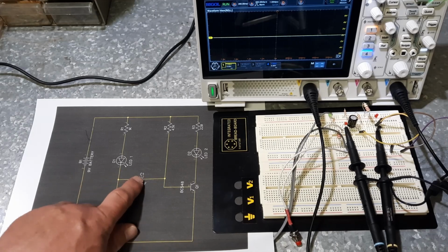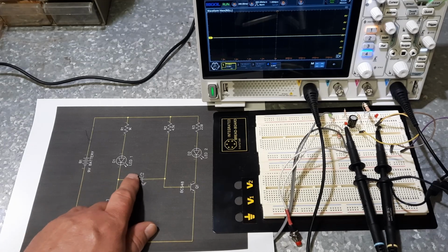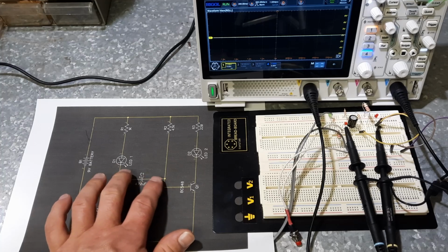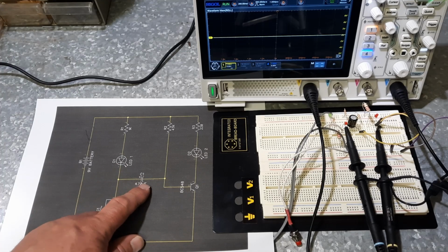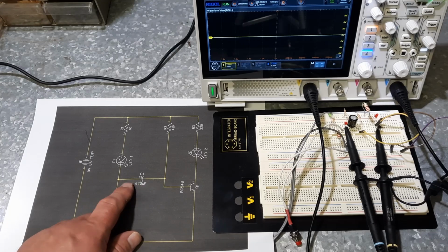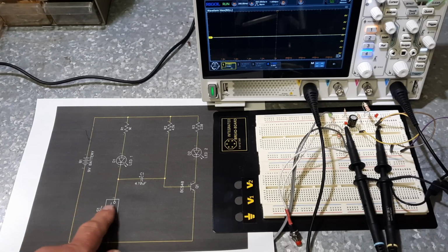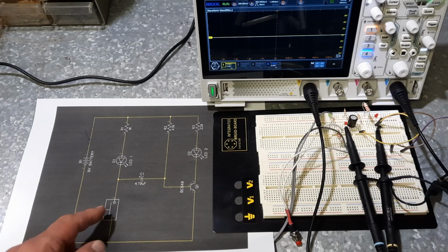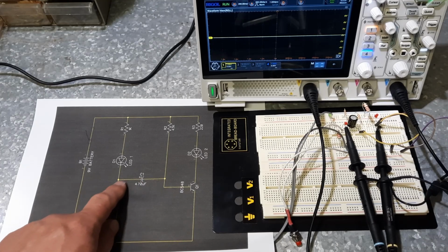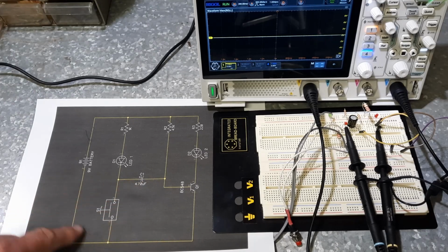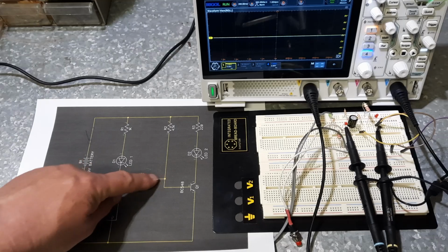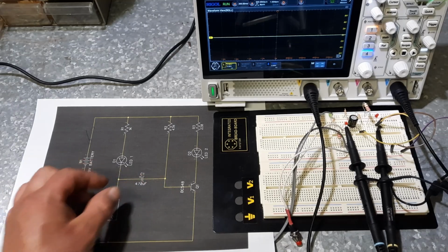Well, there's a charge on this side of the plate, which is pressure in the capacitor. So what's it going to do? If you give it a path to discharge, that's exactly what it's going to try and do. So we've grounded this thing now, or we've shut our momentary switch, which now brings this thing to the most negative part of the circuit. So it's going to come through here, and then it's going to try and equalize itself.